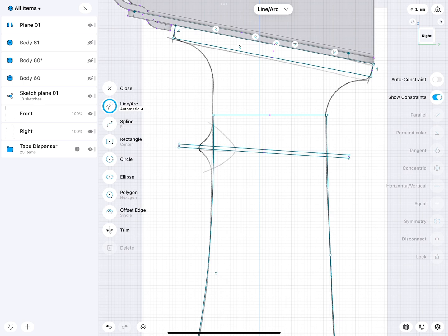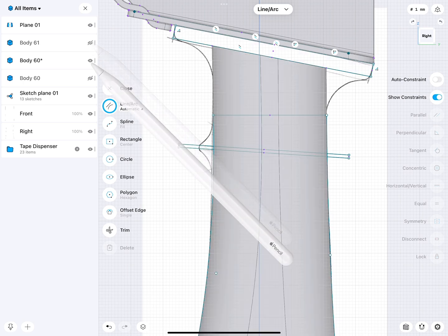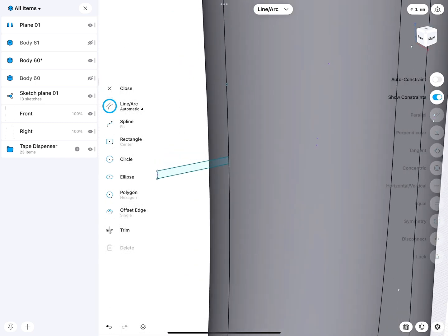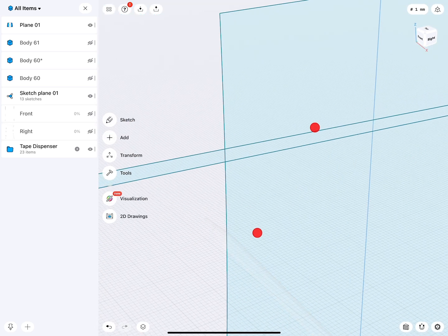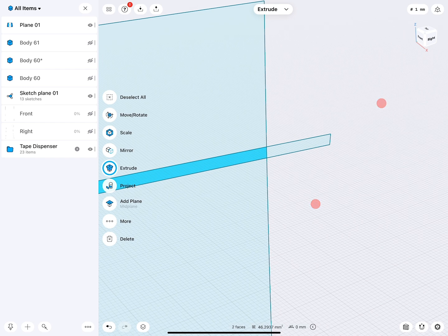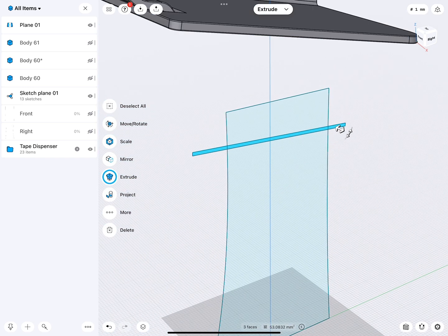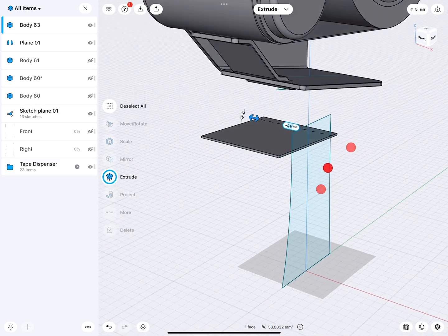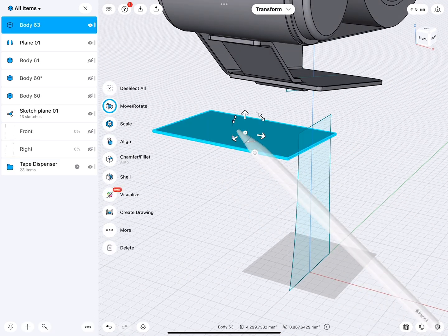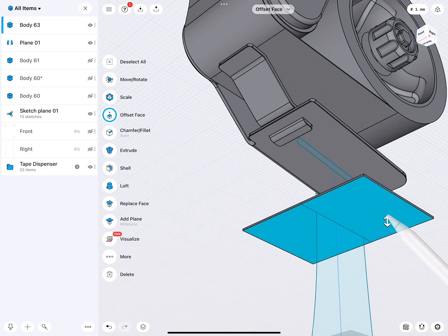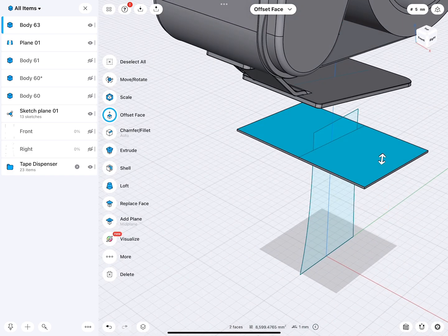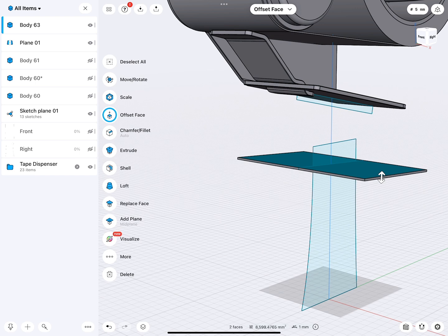So why did I do this? This is kind of like a different process, how to split the body. I will select all these interior faces, extrude this really far, double tap, move this back, and then this could be my Boolean intersect or cut command. I could also, as an alternative now, place actually two split surfaces on each of those, and then do a split.